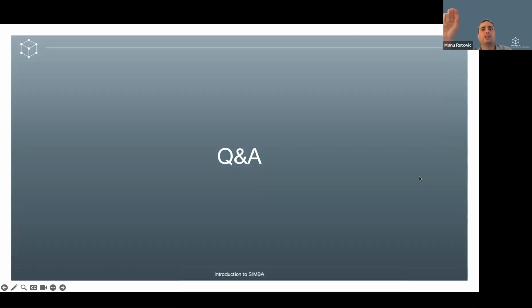Here I'm just talking about Simulink, not about SimPower Systems and other modules. Simulink is not purely digital, but it's pure control, while in SIMBA it's a mix between control and power, or control and analog. So you can do both with SIMBA. Actually, in Simulink as well, but in Simulink you have to know the analytical equations of your analog loop.